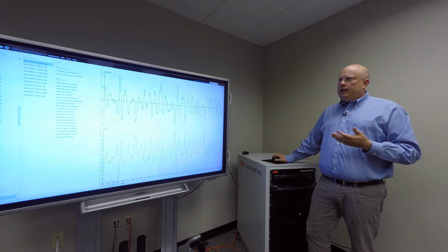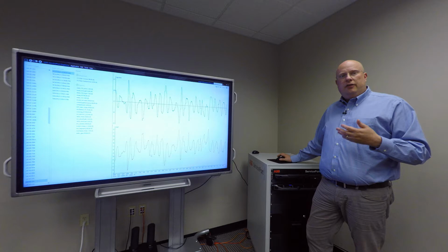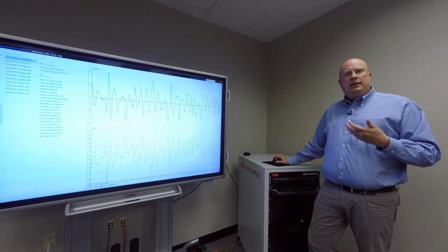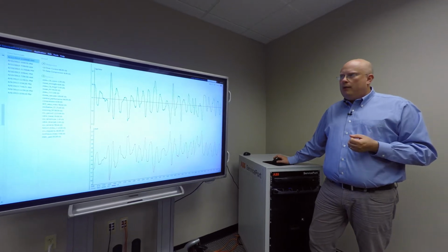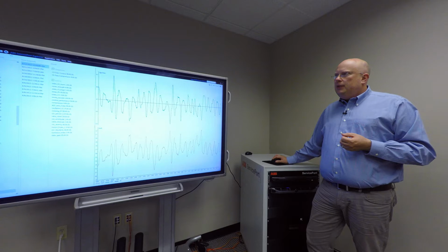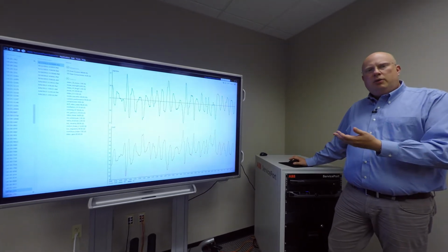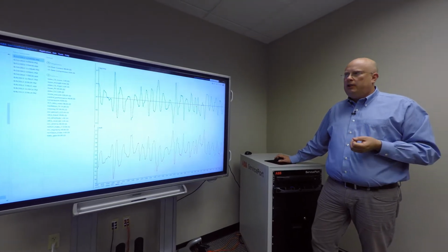Historically, you would ask then the operator, can I please do a bump test? Can I affect the process in a way so I can get useful data back to do a modeling to come up with better tuning parameters? But the data we have in the loop performance channel probably contain one of those bump tests already that happen naturally.